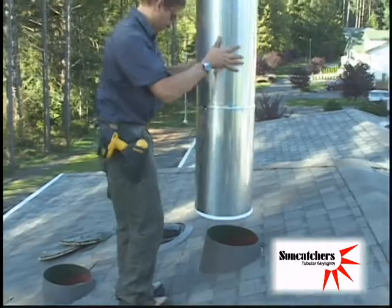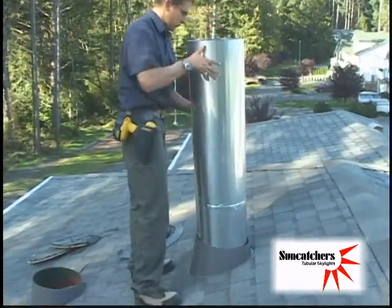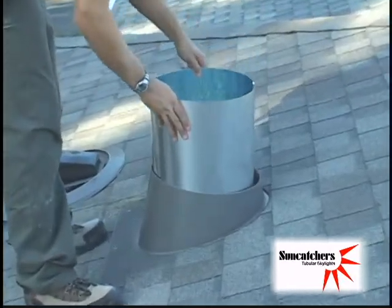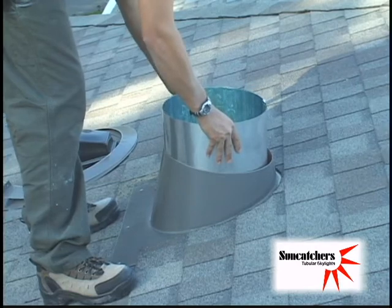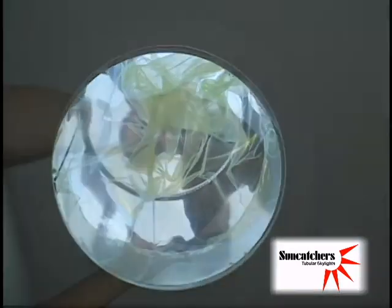Carry the completely assembled pipe onto the roof and lower it down through the flashing. For aesthetics, it is best if your taped seam is rotated to the back of the flashing. Lock the white foam tape into the white ring by gently twisting the pipe while applying slight pressure.